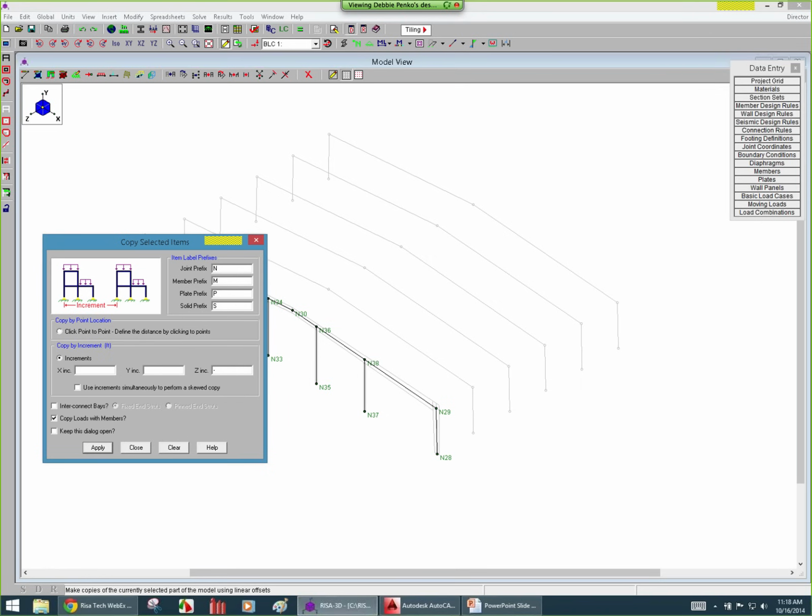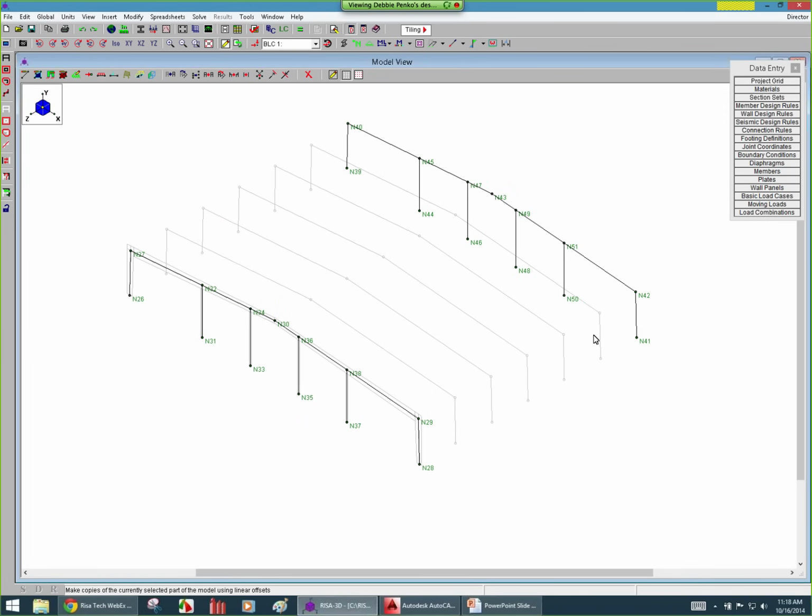Always, you can see that global. This was the positive direction. The negative direction is away from the capital Z. And I'm going to say negative 90, apply, and that's where it then draws in my end wall. So I've got the ability here now to see all of my members in place for my frames. Now I just need to start worrying about those purlins and tying everything together.